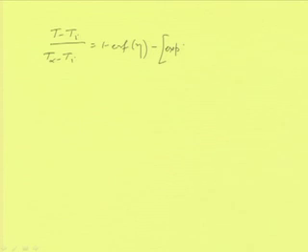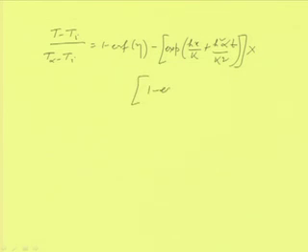So, when we have this kind of boundary conditions for case 3, the solution of the above equation becomes like this: (T minus T_i) by (T infinity minus T_i) equals 1 minus erf of eta, minus exponential of (h x by k plus h square alpha t by k square) into 1 minus erf of (eta plus h root over alpha t by k). So, this is the solution.